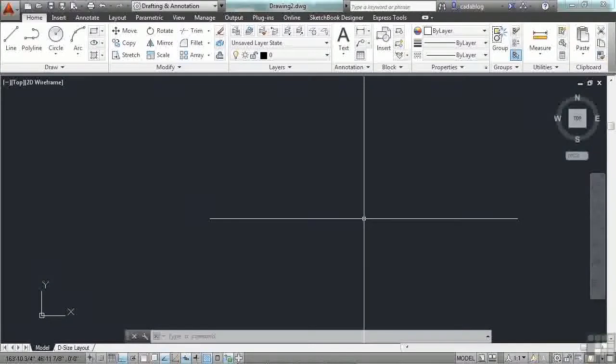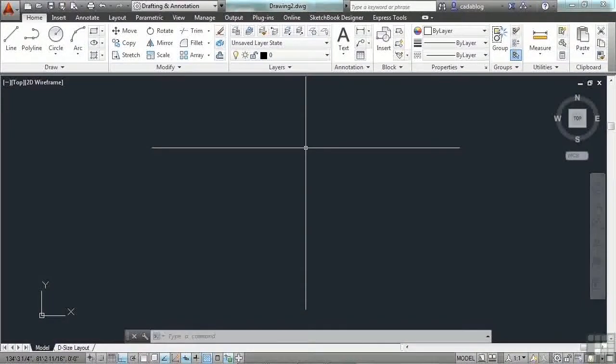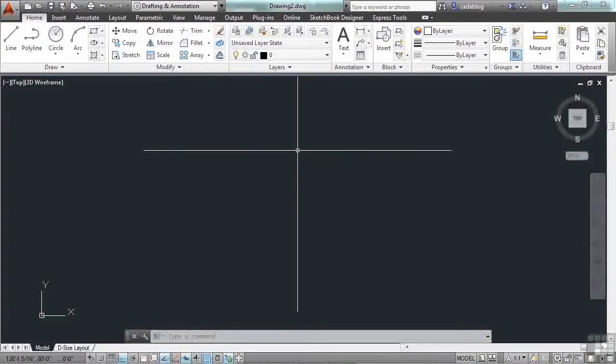In fact, we've drawn many polylines already using the rectangle command. I like to use the rectangle command as a great example because it's very quick to do. Two points, and you have a nice shape that's easily defined, seen, and worked with. But drawing a polyline can be accomplished using the exact same methods that you draw a line with. So the previous section here in this chapter will be applied directly to a p-line exactly in the same way. After all, a polyline is just a set of lines that are connected together.